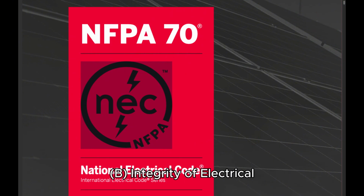C. Integrity of electrical equipment and connections. Internal parts of electrical equipment, including busbars, wiring terminals, insulators, and other surfaces, shall not be damaged or contaminated by foreign materials such as paint, plaster, cleaners, abrasives, or corrosive residues. There shall be no damaged parts that may adversely affect safe operation or mechanical strength of the equipment, such as parts that are broken, bent, cut, or deteriorated by corrosion, chemical action, or overheating.